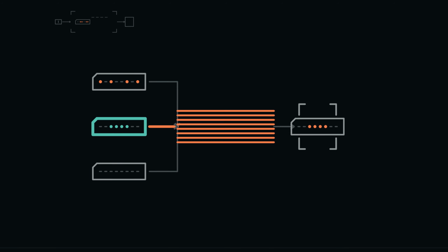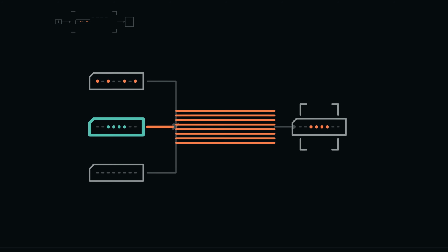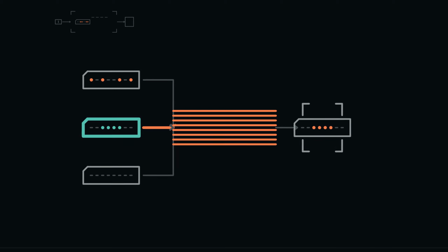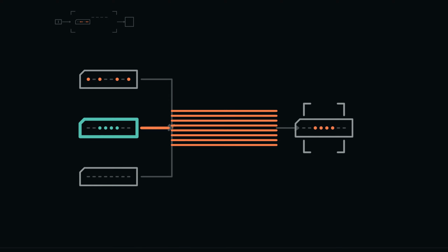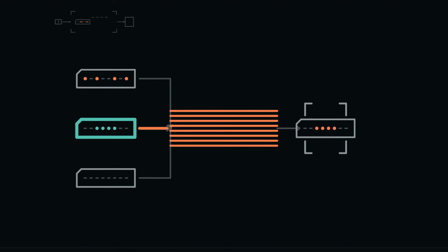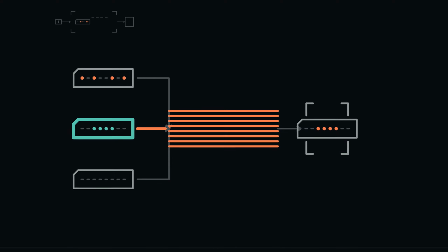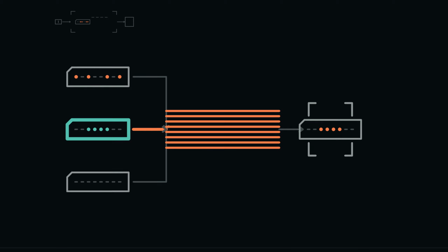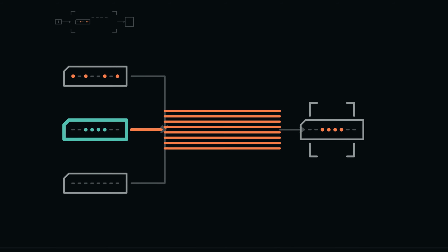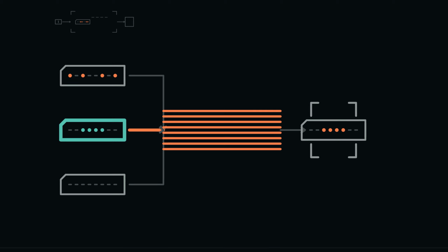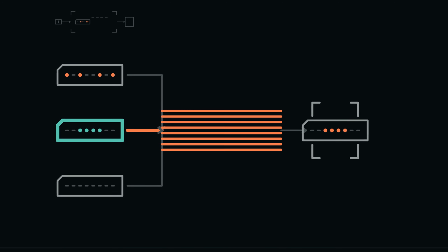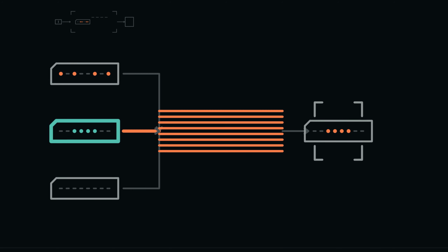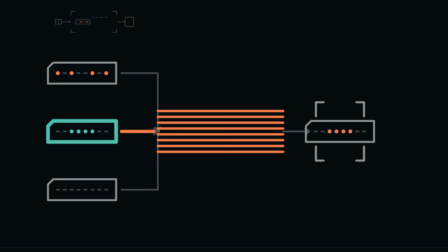Watch register R2, which holds hexadecimal 3C. Its output is normally disconnected from the shared lines. When the controller enables R2 as the one driver, each of its 8 stored bits determines the corresponding bus line. After physical settling time, the receiving rule classifies the lines as the same pattern. The highlight marks causal relevance. It is not 8 glowing pellets in flight. In the SE8 trace, a valid bus transfer therefore names one source, one value, and one destination. When no transfer is active, the bus record is invalid rather than an invented 0.